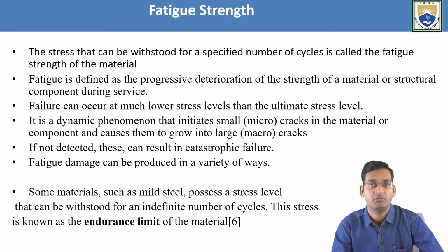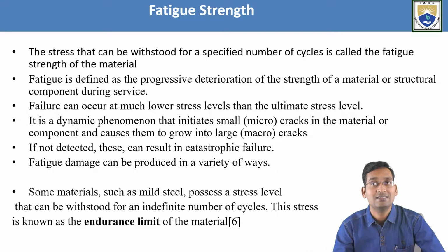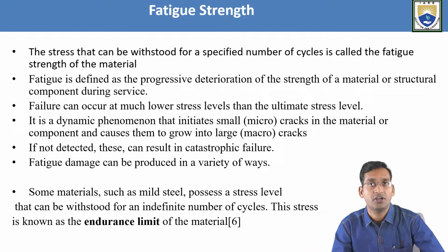That is for one time. If suppose one time we are hammering, once it reaches the maximum ultimate stress, then only it will break. But because of the fatigue, that is the repetition of the load, it can crack or get damaged much earlier than the ultimate load, depending upon how many times stress is acting on that material.